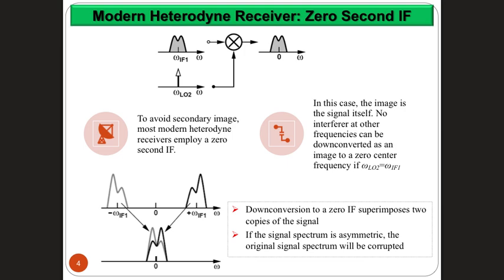It simplifies the design. It makes specifically the design of intermediate filters so that they can do the job of image rejection and channel selection in an easier way. Okay? But that comes with a challenge, the fact that now you suffer from the image 2 times. So it's not only one stage where you suffer from the image, you suffer from the image in 2 stages. First IF and then second IF. Tamam?